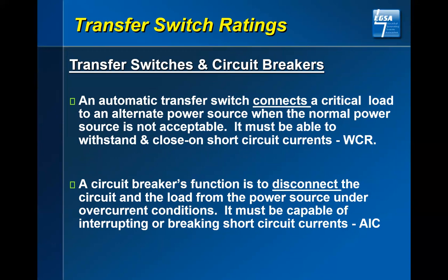In the case of a transfer switch, this is where you see not only the term withstand, but you see close on. As we stated earlier, you are going to start that alternative source, whether it's a utility or a backup generator, you're still going to close into that fault because it's still there. The switch must be able to be operated. It cannot fuse together. No linkage can break. It must be usable. We are requiring the upstream device, the circuit breaker, the fuse to clear us. But the 2 differences is an AIC of a circuit breaker is different than a withstand close on.